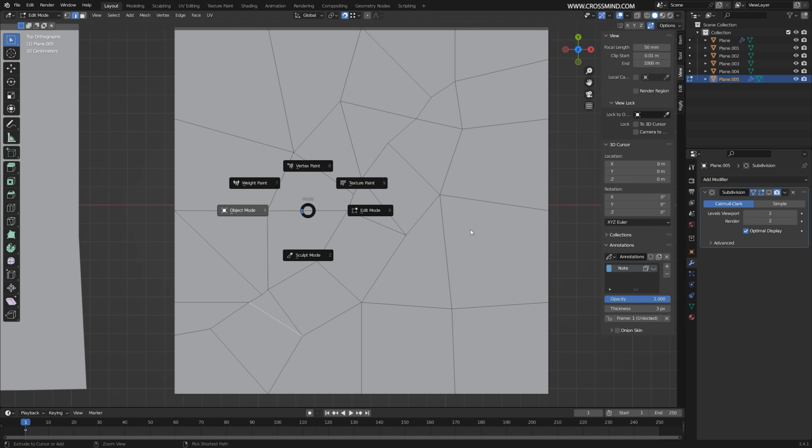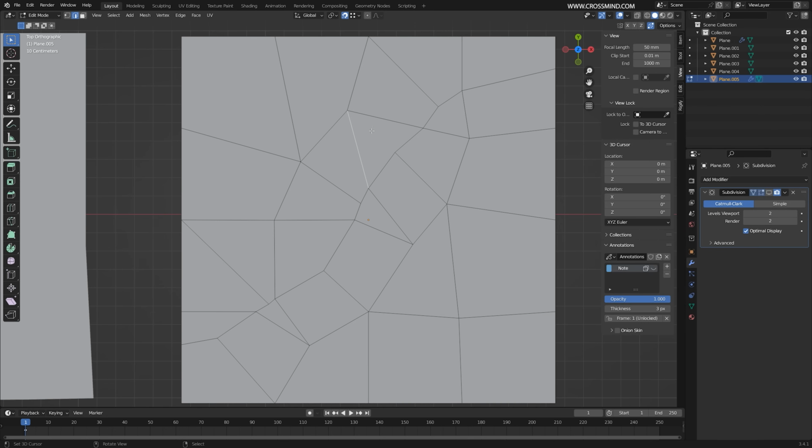What I'm thinking is I can have these loops flow in this direction and these loops flow something like this. Now to make this happen, I'm going to just clean up a bit. So if you find it too difficult to visualize where to connect these triangles and how to clean it further, what you can do is simply select a few of these loops which are harder to visualize, Control Delete to dissolve. Now you have a clear path in front of you.